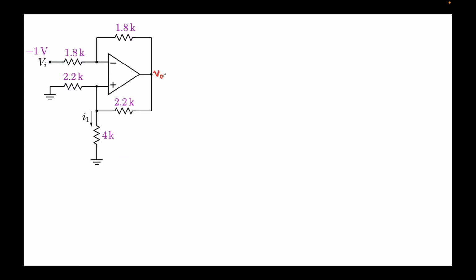So this is the node voltage V0, this we have grounded, right? Let's call this voltage V1. If this is V1, this will also be V1 because it's just a wire. In the first step, we'll label some currents. Let's call this current I2, this current I3, I4 and I5. Again, no current can flow here or here.